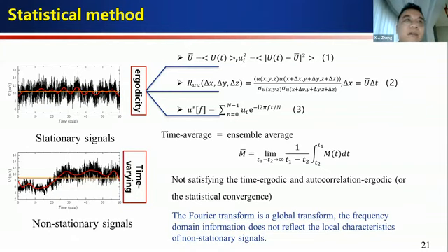In the existing statistical theory of turbulence, the statistical moments of wind velocity, such as mean wind velocity, turbulent intensity, and the two-point correlation, etc., are all time averaged quantities, which are assumed invariant with time. That means time average and ensemble average are equal.